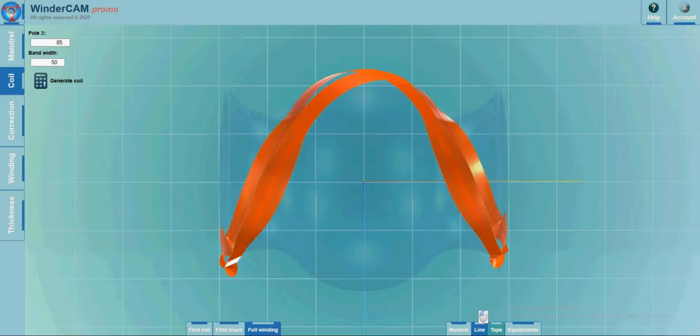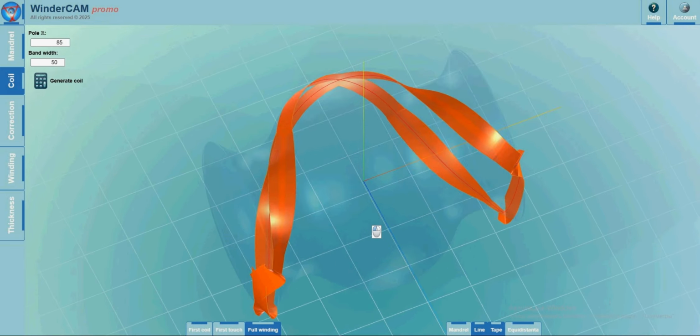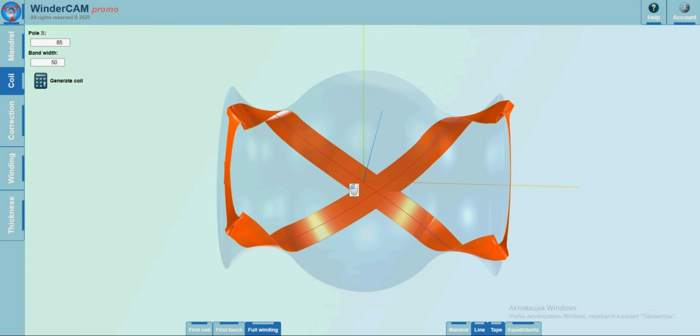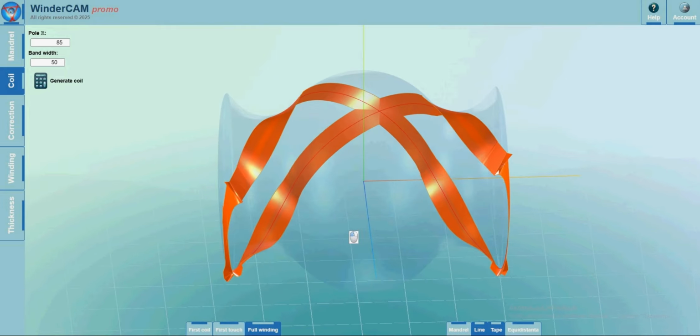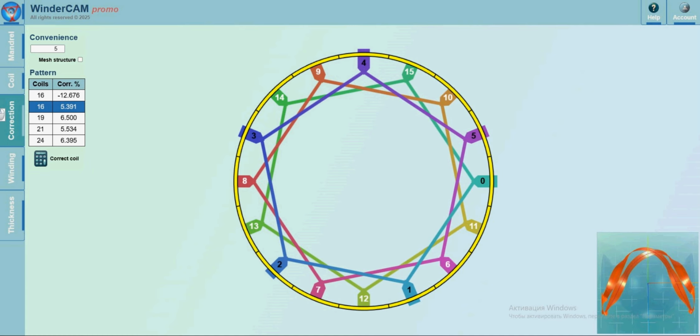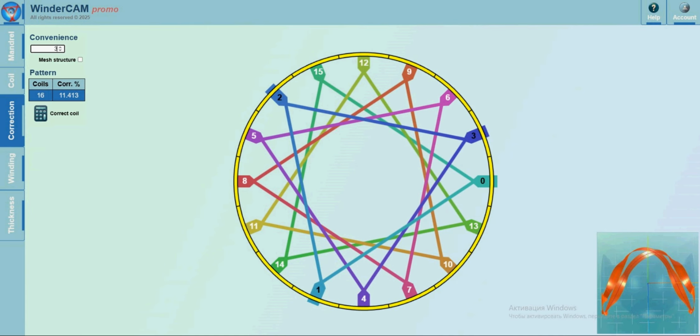Exactly. The rubber tape is relatively wide. After vulcanization, it transforms into a solid, durable rubber matrix. The cord mesh provides the structural reinforcement, much like in traditional composites. Together, they form a flexible but strong connection between two pipe sections, capable of absorbing thermal expansion and vibration.